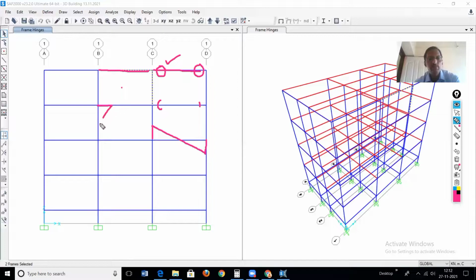It is like this. Here also the flexural stresses are maximum at the ends only. These are the bending moment diagrams under lateral loading, like earthquake loading. Therefore, the end zones are very important. There is a high concentration of flexural and shear stresses, so if failure occurs, it will be at the ends only.